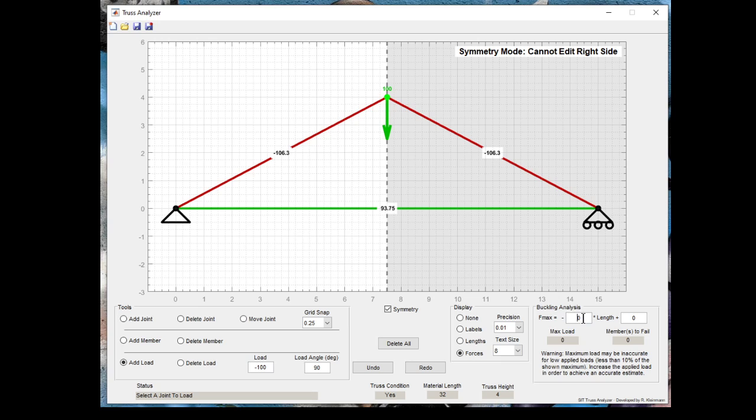So let's say we had a bunch of data that we did in week 3. We could put all that data together in one collective Excel sheet, lay out the data, LU in the X, failure load or PCR in the Y, and then we could apply a linear trend line and get this equation and put it in here.